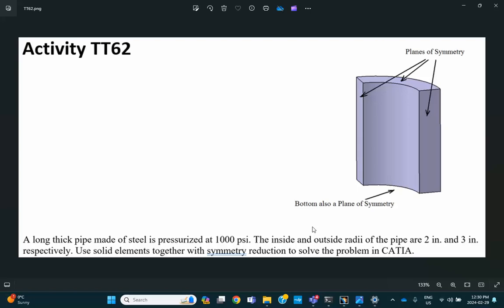In other words, we can pretend that you can take a sector of this tube, and the top of the sector and the bottom of the sector do not translate perpendicular to it. That is true. So we can view the top and the bottom as being planar symmetry, as if in a roller condition.